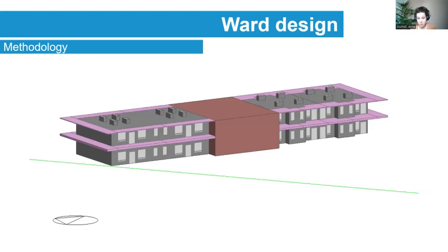To assess the performance of the building, simulations were undertaken through specific software that allowed to calculate the air change rate of every single environment of the healthcare structure on an hourly basis. Simulations were performed for the entire building. However, in this presentation, we'll focus on the results considering the bedrooms only, which are the most critical environment of the entire facility. In particular, since the wind has a primary direction, a windward room and a leeward room were considered in the study. For each site, the simulation has been conducted for the worst week of the year in terms of outdoor temperature and wind speed.